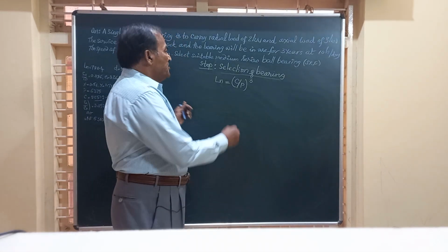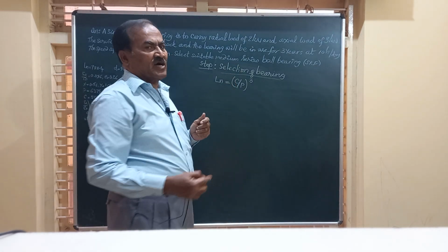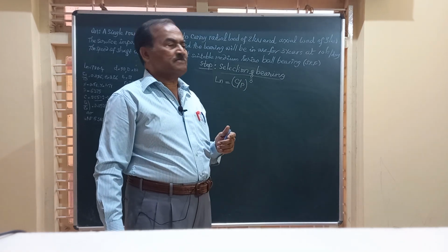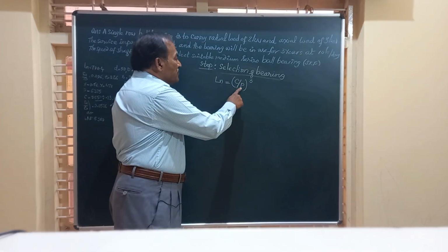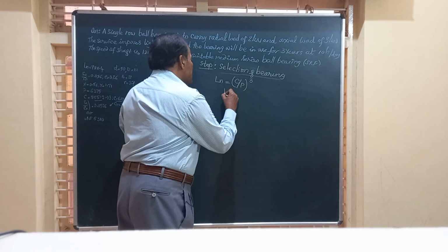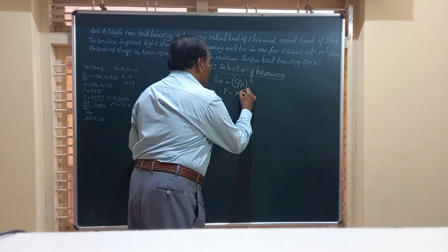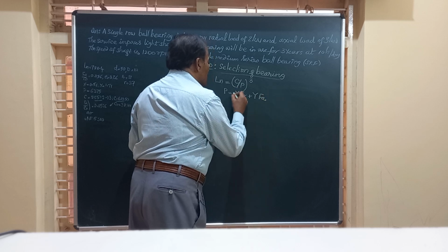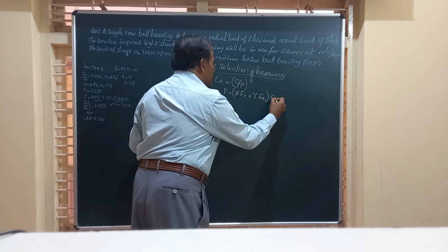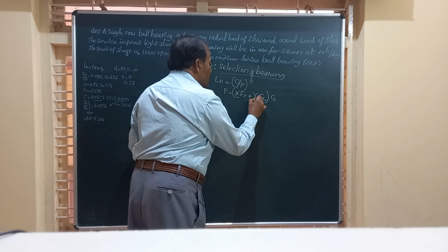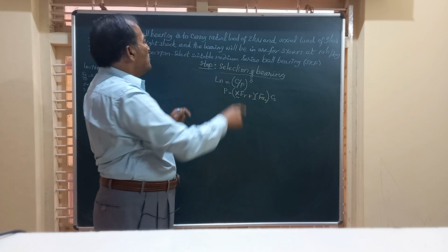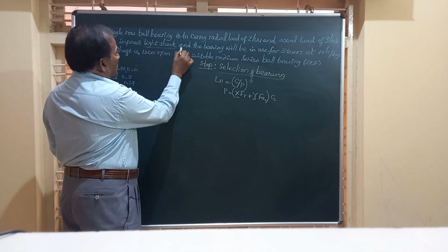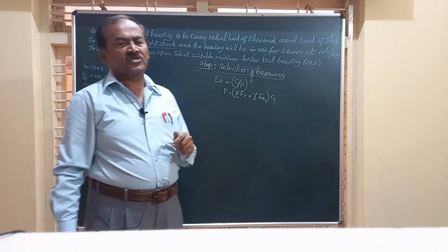Here, we do not know the diameter of the shaft or the bearing, and hence we cannot find the value of C. So to find P, which is equal to (X Fr plus Y Fa) multiplied by the service factor, we should know what X and Y are. The service factor is known to us because the bearing is subjected to light shock.